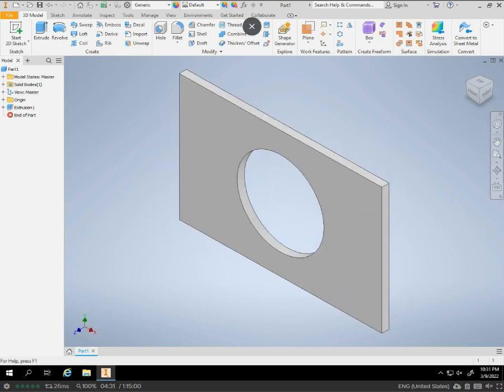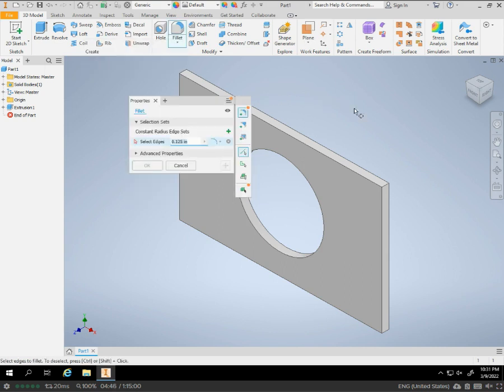All right, so our next step, we're normally going to put another sketch and then start doing something else. But before we do that, this time we're going to use a new tool, which is the fillet. The fillet is going to round the corners and edges like we use fillet in AutoCAD and Revit. You can actually use it in 3D space. So we're going to set the radius to 1,